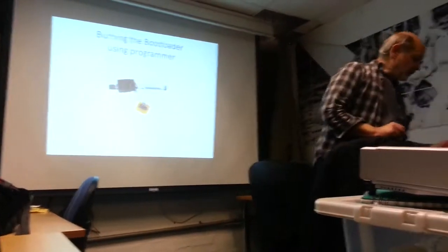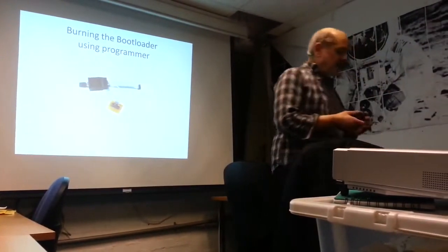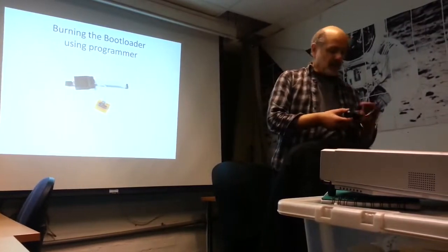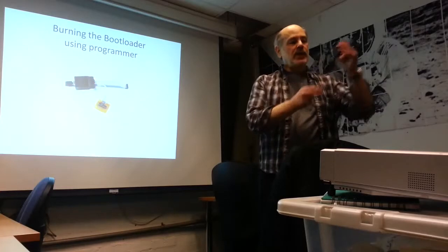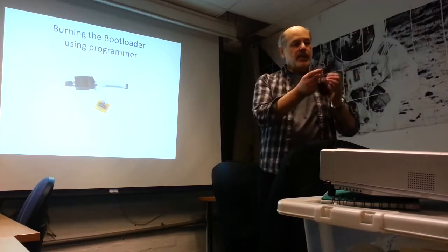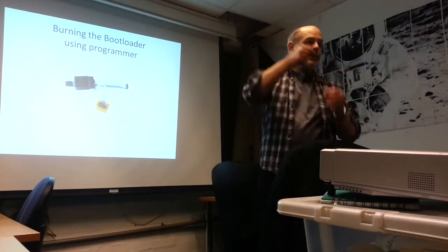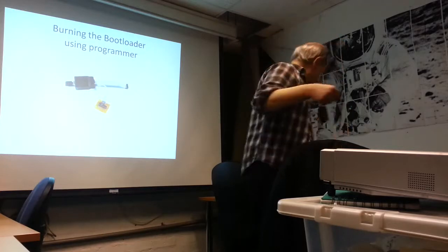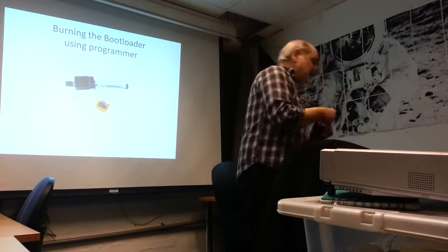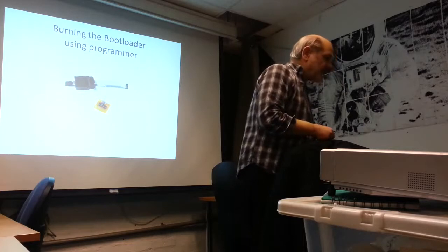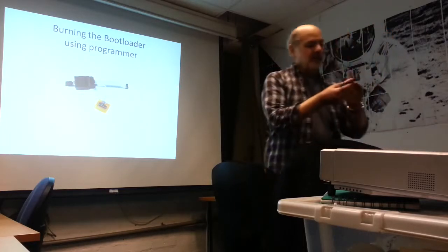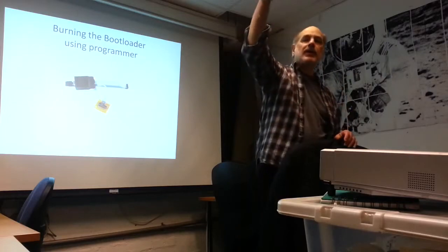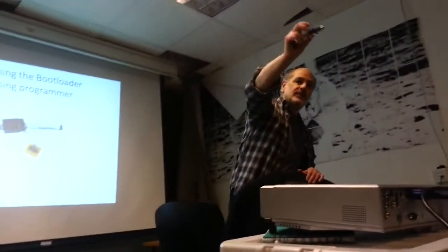And once it's compiled, typically the way the bootloader is put on is with a programmer. Here is the example programmer. One end of it connects into USB. The other end plugs into that little 6-pin header socket that you typically see on an Arduino board. There are other kinds of programmers, such as this clone programmer, a small USB one from China.